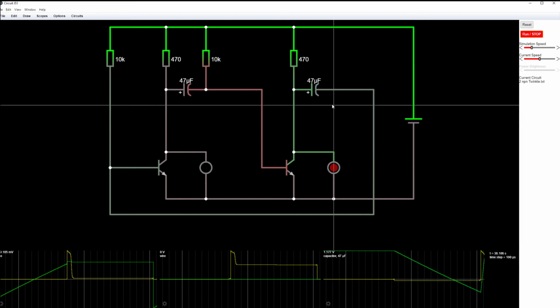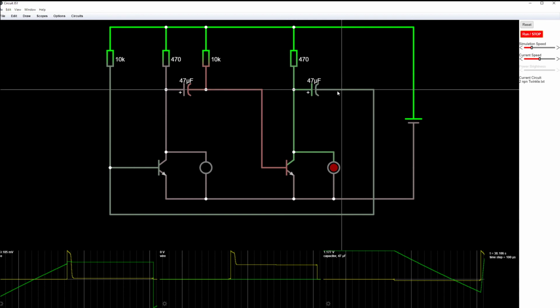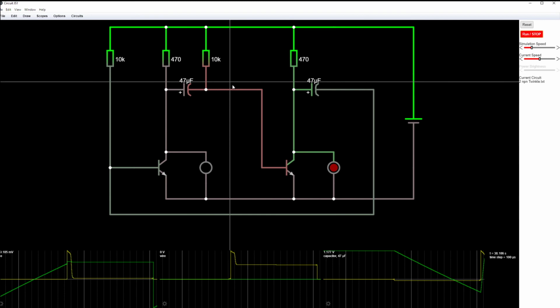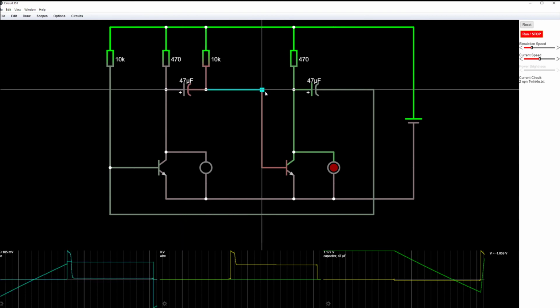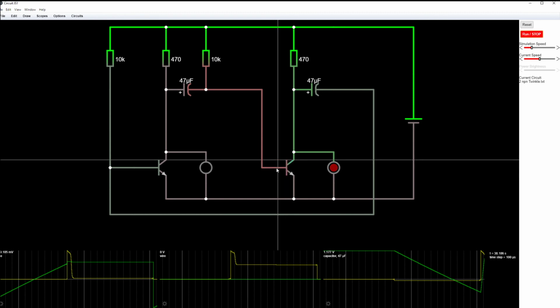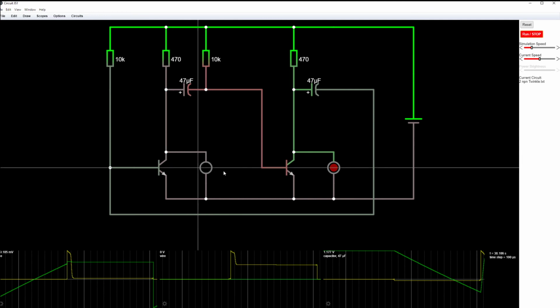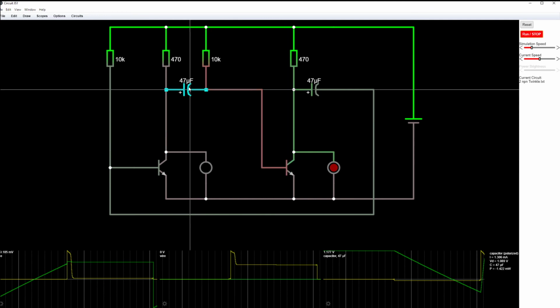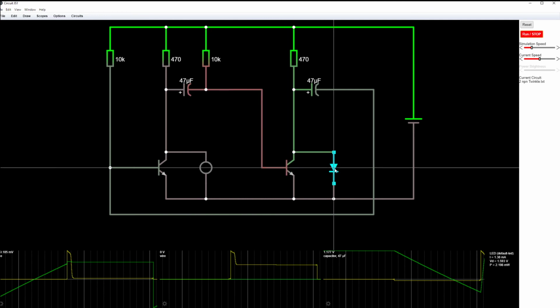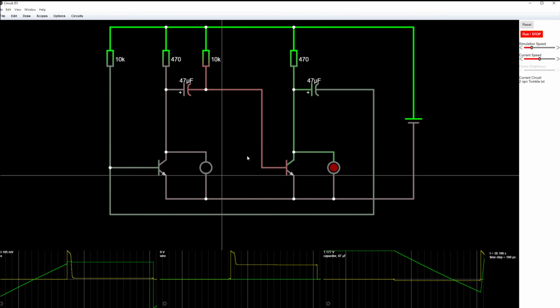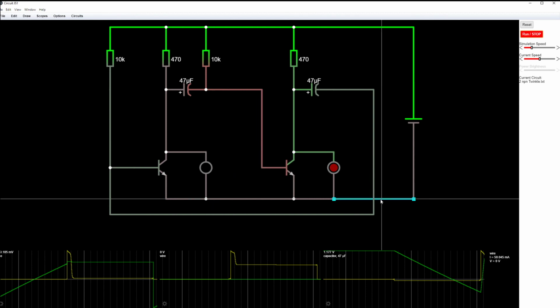And secondly, the relative charging of the capacitor is what's determining for the transistor to open and close. So it's a very simple way, using just resistors, capacitors, and transistors, to make one switch turn on and to make two lights turning on.